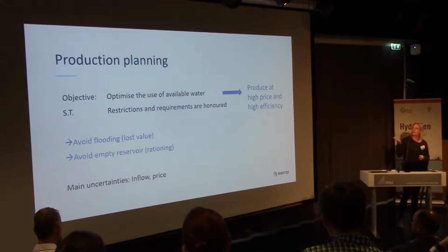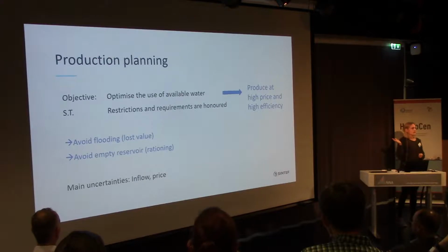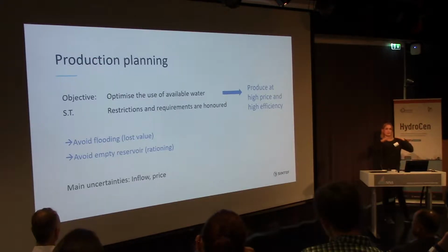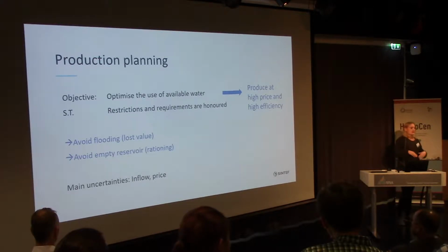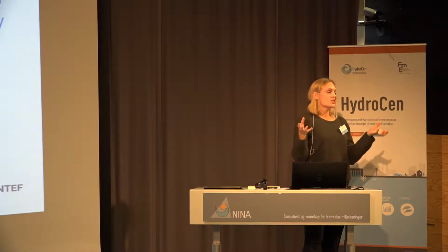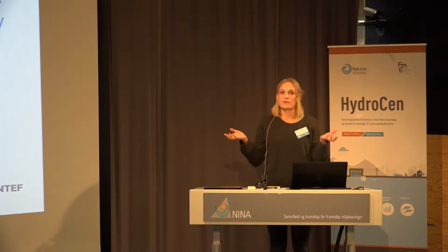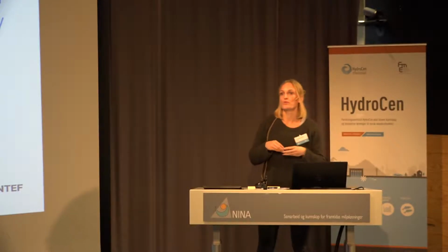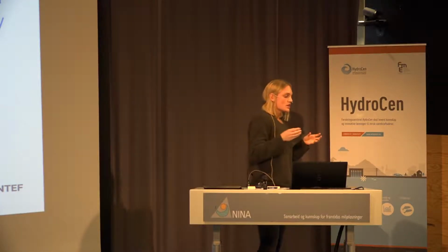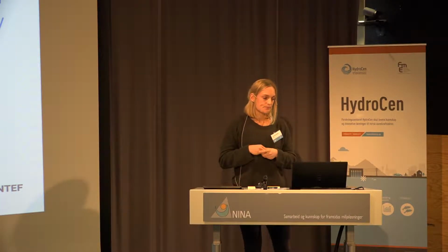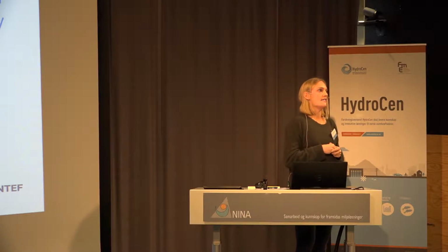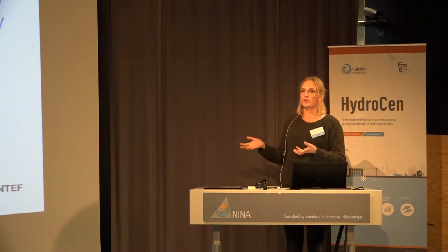Produce at high price and high efficiency, but also consider your reservoir and the level in your reservoir. So we already talked a little bit about this, right? You have a maximum level and a minimum level. And we want to avoid flooding or spillage, because that's lost value. And we want to ensure that we have available water, because we don't want to end up in a situation where we have rationing or curtailment. And also, if you don't have any water, you don't have any options. You don't have any cards to play, right?